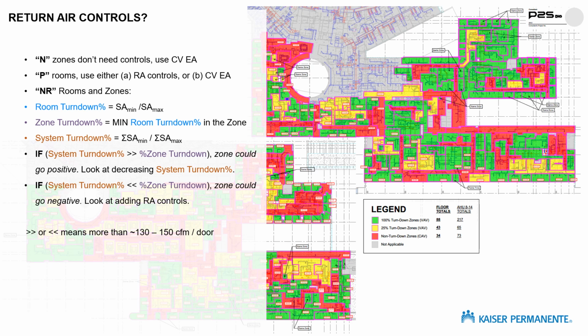Well, in that case, a single return air control, at a main duct that just shuts down return air to that quadrant of the building or severely limits return air to that quadrant of the building could be the right means. Now, these deltas, you'll see that I'm using this sort of double greater than or double less than sign, because these deltas do need to be reasonably significant.